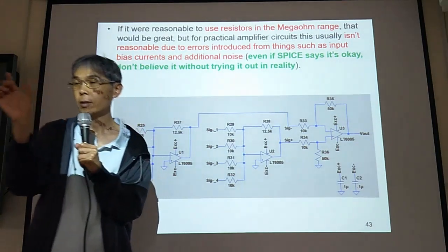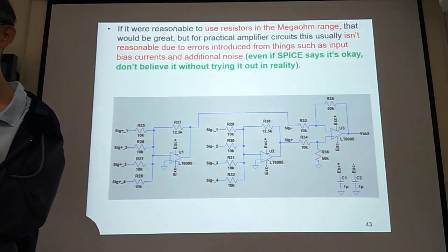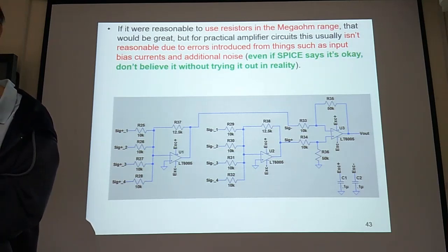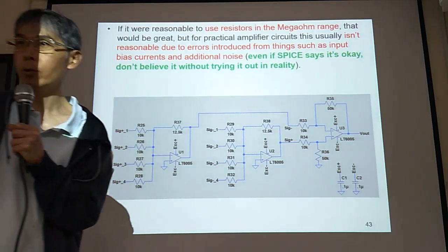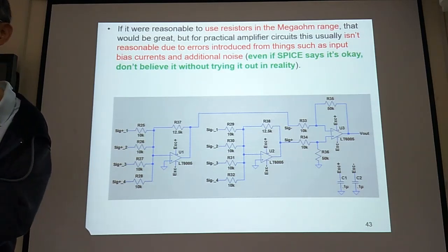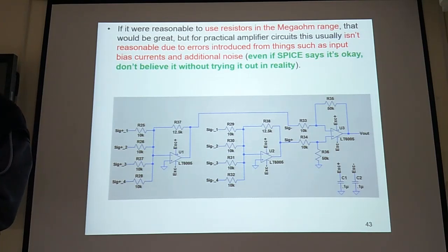Resistor is noise. Even if you increase to 600K, the thermal noise created by the resistors will be large. Remember, the noise density is 4kTR. The resistor noise is 4 times Boltzmann constant times temperature times resistance. So large resistance will increase the voltage noise due to the resistors.